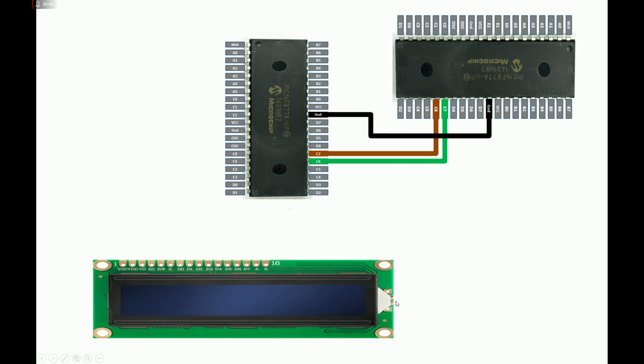As you can see, it's a 16x2 LM016 LCD, easily available in the market. Now you can see this is a 10K potentiometer. We need this to connect this LCD with the PIC because it will be used to adjust the contrast of the LCD. So you need this. Now it has 3 pins, 1, 2, 3, also mentioned on the body as well. You may use other type of potentiometer as well, doesn't matter, but these ones are more accurate. So I suggest you use the same.